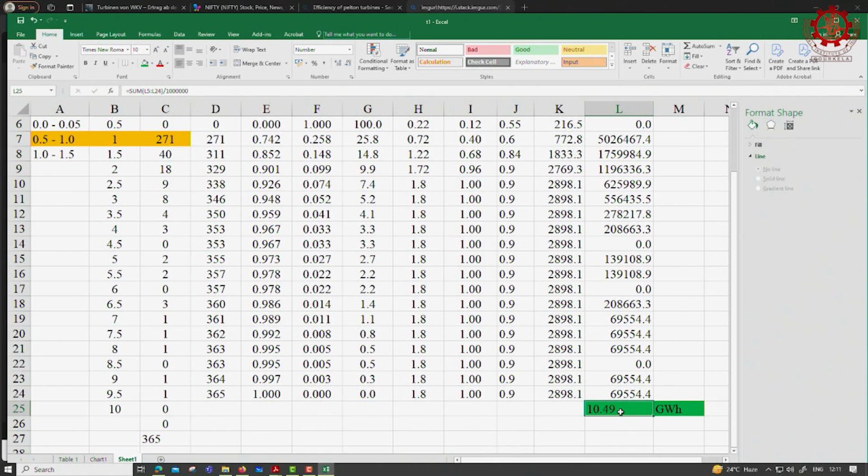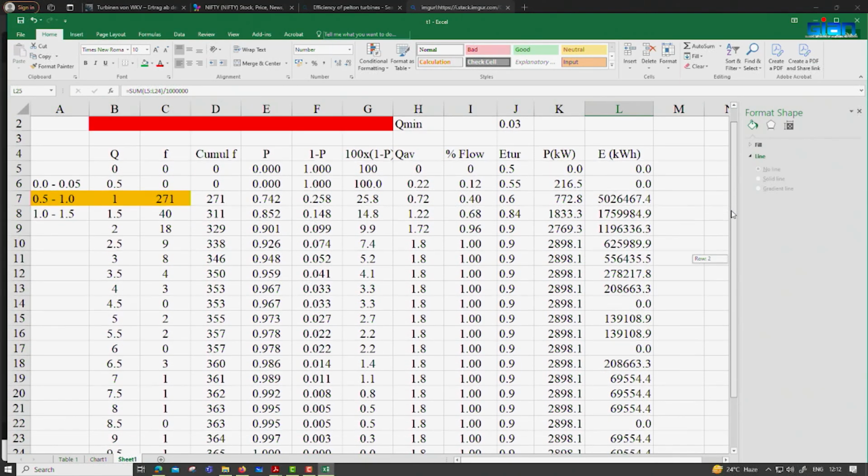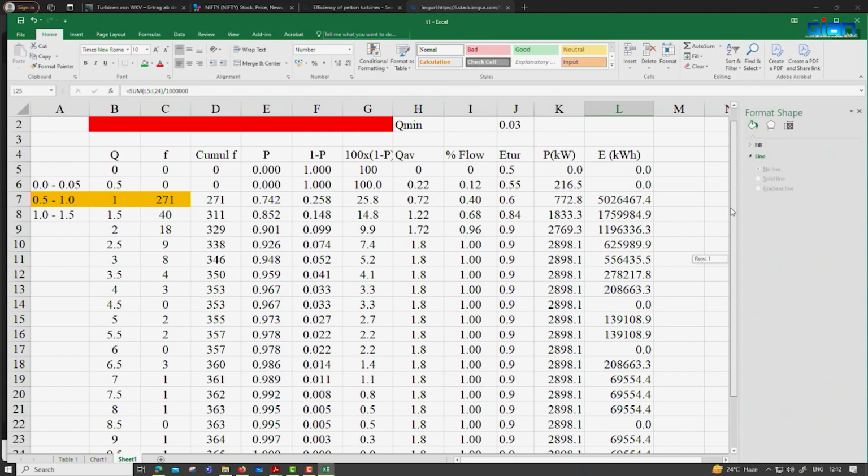You must get offers for all three from the manufacturer, right, and then with certain assumptions you can get the civil costs also approximately done, and then the total project cost, then do the economic calculation. But your annual energy generation for the three types will be different. Now, you can see this is 10.5, previously Pelton had 13.1, right. So, your annual income is going to be different and project cost will be different, because they will charge differently for the two turbine types. I hope I make sense to you.